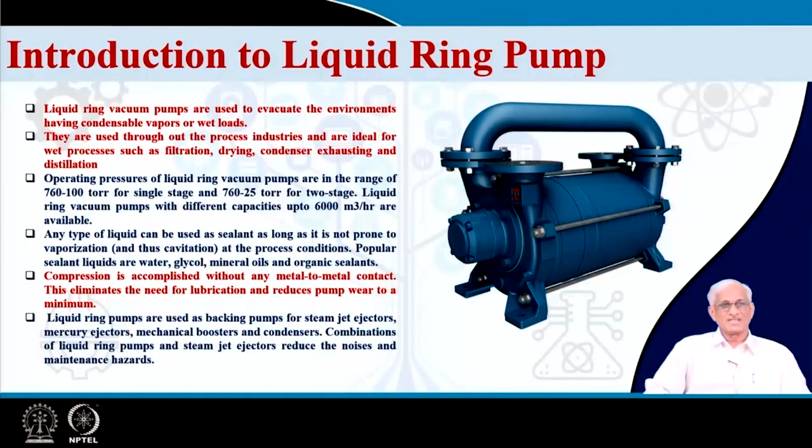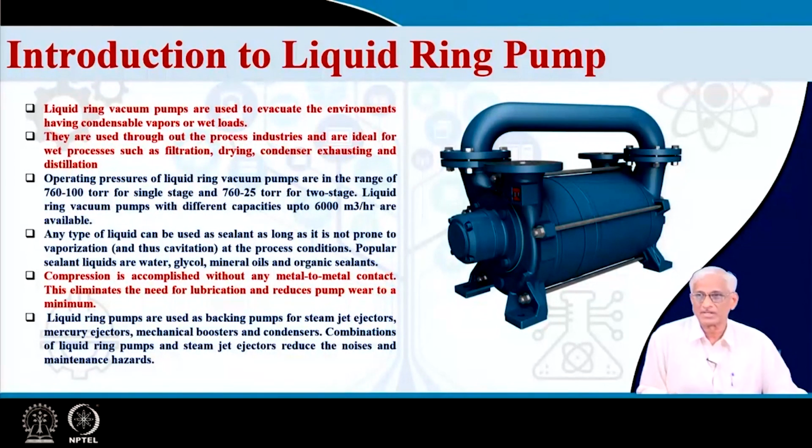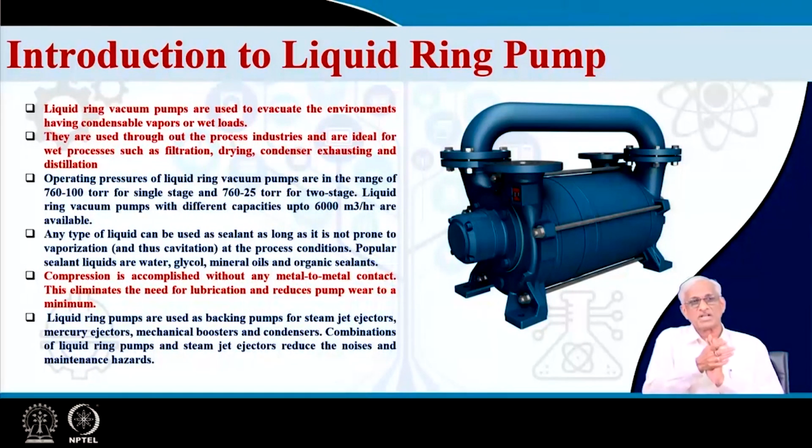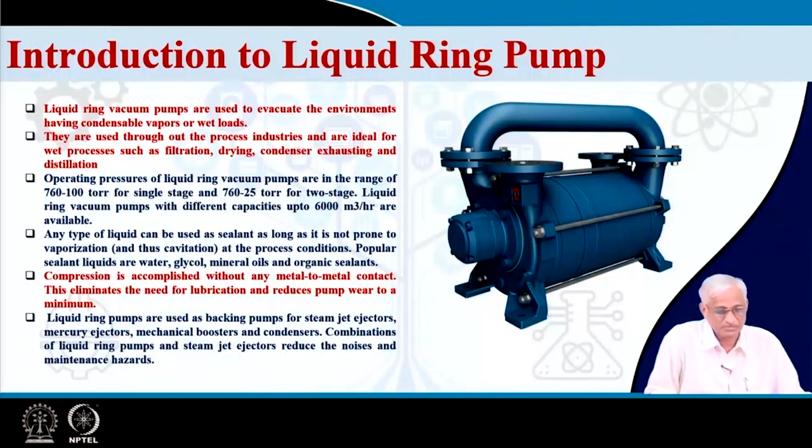Whereas here sealant purpose is the main thing. Then comes coolant, then a little bit of washing effects are there. You cannot talk of lubricant effects here, okay? Because there is not much frictional heat produced with metal to metal type of thing. We will see when we see the constructional aspect of it.